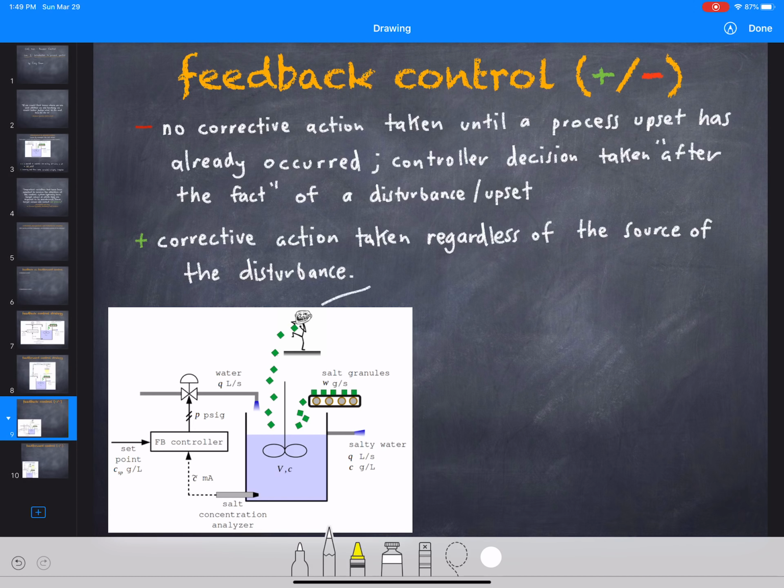For example, this here is disturbance number 2. And it is a troll. And this troll is dumping salt granules into the tank, right? And the thing is that even though we might not have anticipated this disturbance, because the disturbance we were considering is W here, it effectively doesn't matter where the disturbance comes from. Your feedback controller is going to measure that deviation in the salt concentration and then take action.